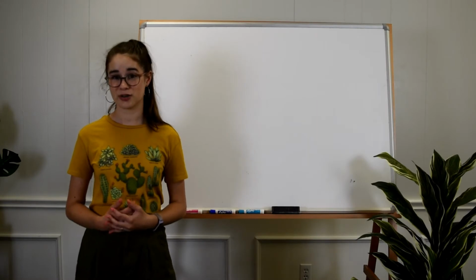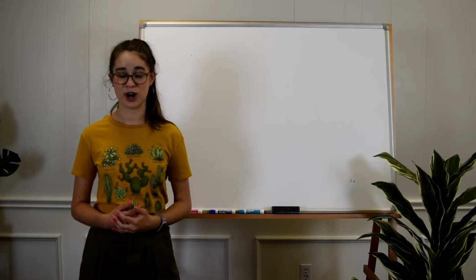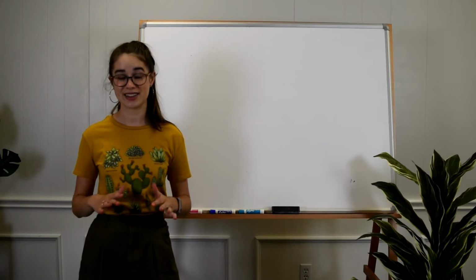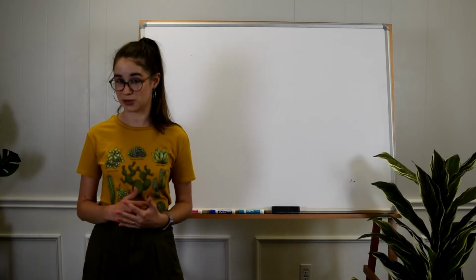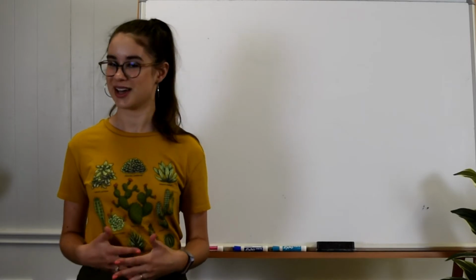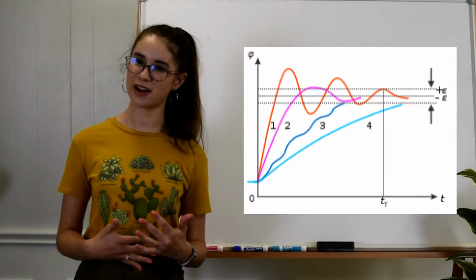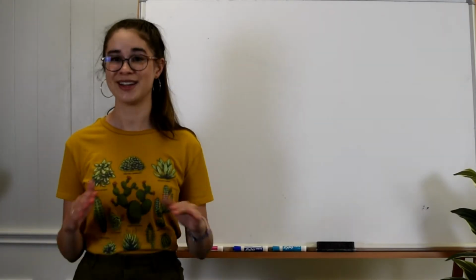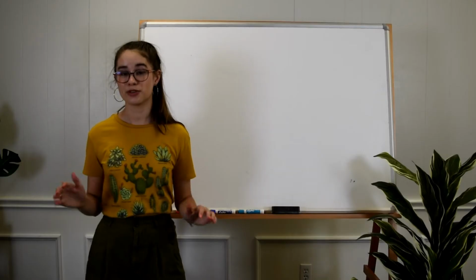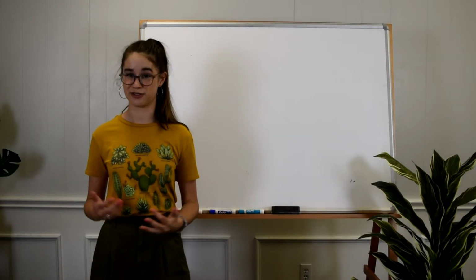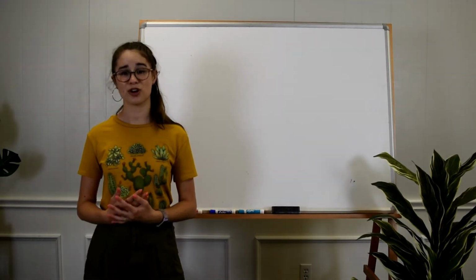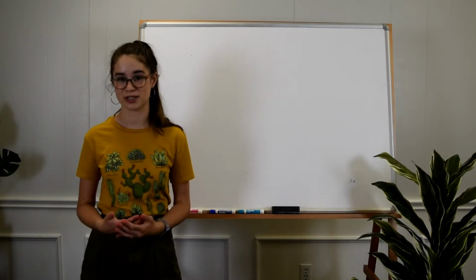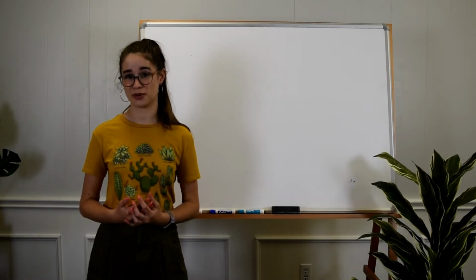Now, the important thing to note here is that while the system response to a constant input is a point on our Bode plot, the Bode plot is not the same thing as the plot of a step response. Those graphs where a system reaches a steady state value, when we analyze rise time and settle time and all that kind of stuff, are not the same as a Bode plot. Both graphs are useful, they just give us different information. Bode plots are all about mapping the particular solution over a variety of input frequencies. It's not about following one input with respect to time.